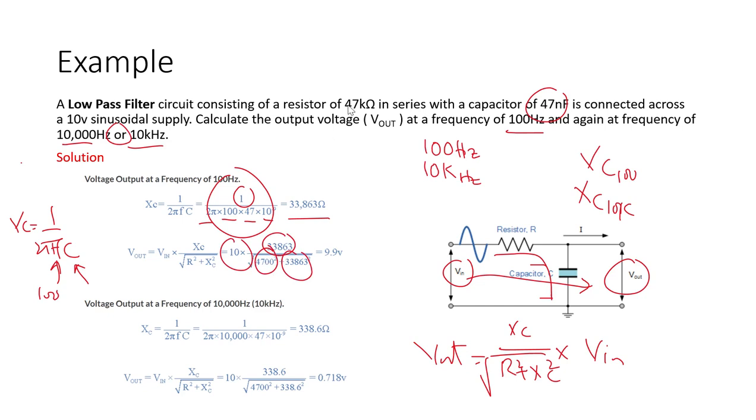So resistance is 47k. So this is not 47k. This is 4.7k as we see in here. I was thinking how can this thing be wrong. Okay, so this is 4.7k, and this nomenclature was, I guess, used in the lab as well, that 4k7 ohm. So this was 4.7k ohm as written in here.